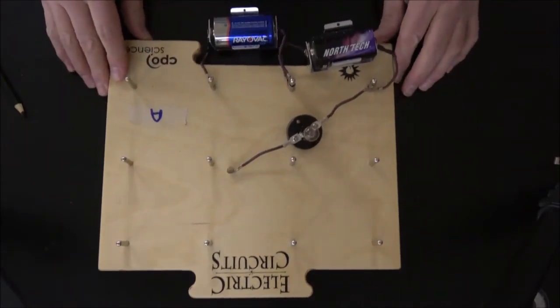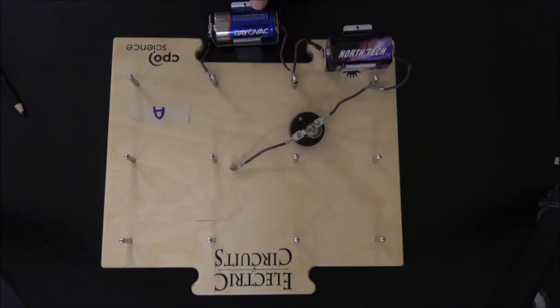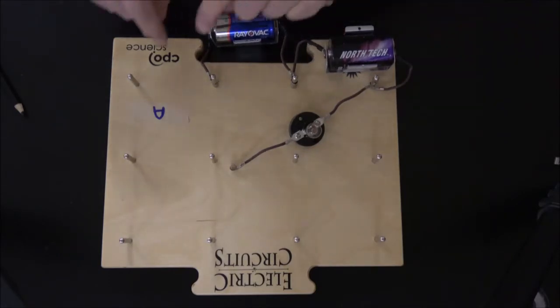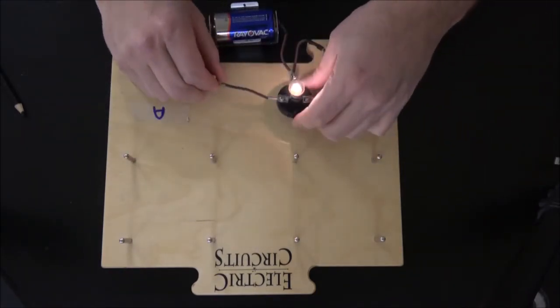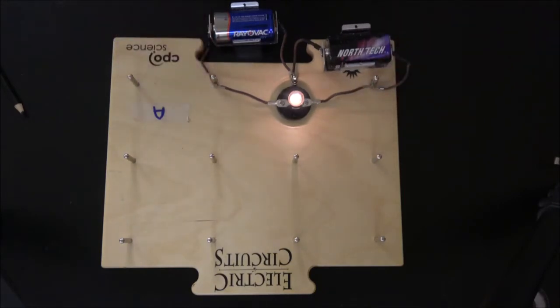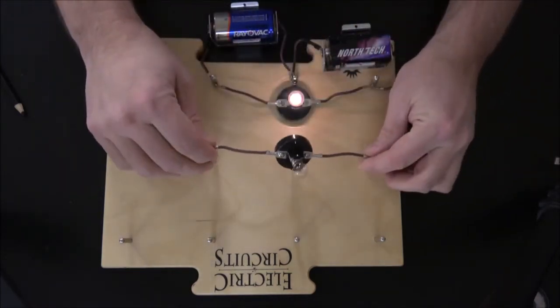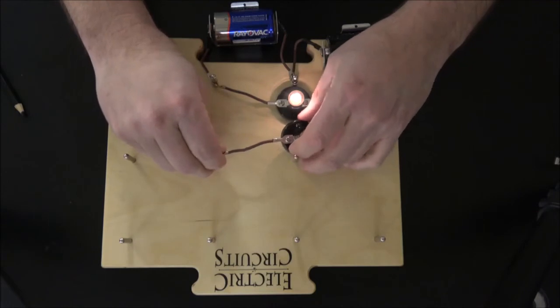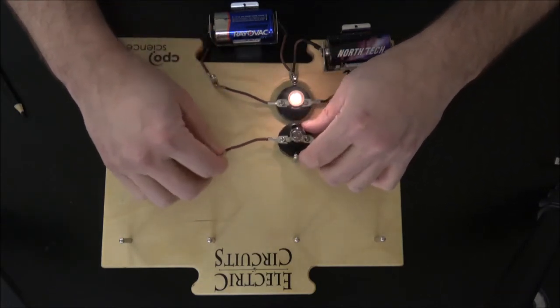To set up the parallel circuits, you're going to have a board like this. Put 2 batteries in here. Make sure they're both headed in the same direction. In other words, I've got the positive here and the positive here, so the current's going to flow this way around. Here's our first bulb. Then, to make it parallel, instead of putting this bulb between the battery and the other bulb, we're going to just set this one right here.